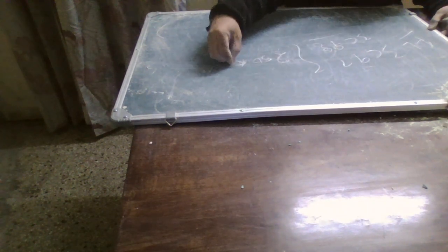As we are going to use a switching frequency of 250 kHz, we are going to use ferrite materials 3C97 and 3C98. These are the ferrite materials that we should use to exhibit a low core loss density at full load, for the switching frequency of 250 kHz.